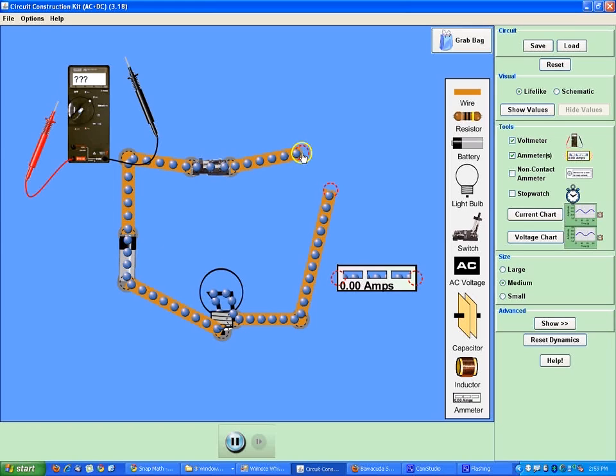To make that work, you take your multimeter. There's several choices here. We want for current, we're always using direct current. So we'll always use one of the DCs, direct current, as opposed to alternating current. And which one, DCV or DCA, do you think is current? DCA, DC amps. So twist your knob, so it's a 200 m next to DC amps.